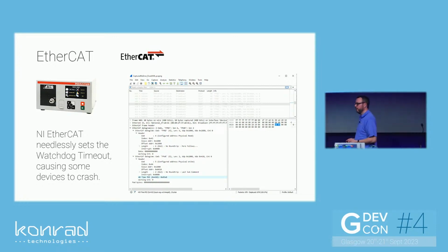Now, if you've used TwinCAT before from Beckhoff, they created EtherCAT, so you'd expect it to be correct, as it were. You can do a similar thing. You can connect it up. It'll discover the devices. It'll turn them into operational mode, and you can interface with them. It's just a way of testing that the product isn't bad, and you haven't got a duff unit. But also, you can Wireshark sniff the communications.